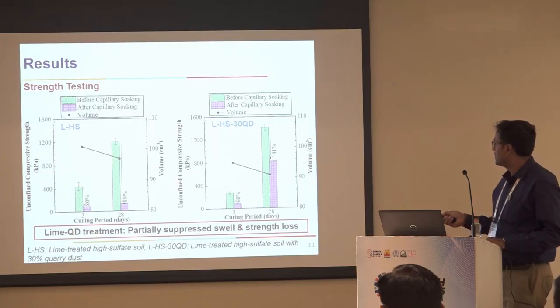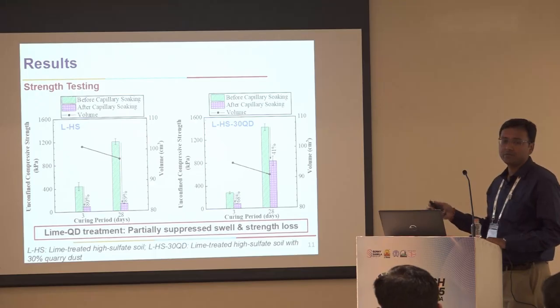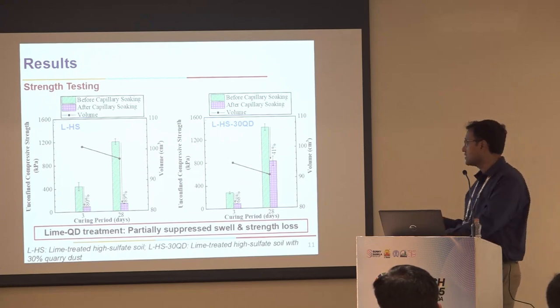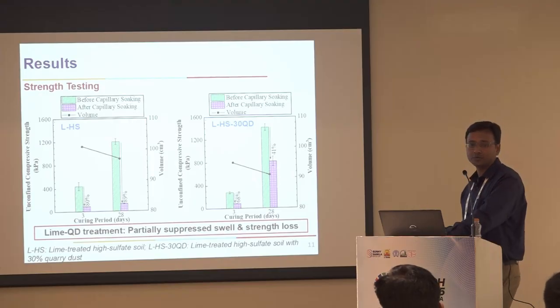The thing is, for 3 days curing, not a significant amount of improvement is observed. That's because, after all, quarry dust has crystalline silica. It does not have amorphous silica as such. So that's why it will take some curing period for it to come into the reaction.